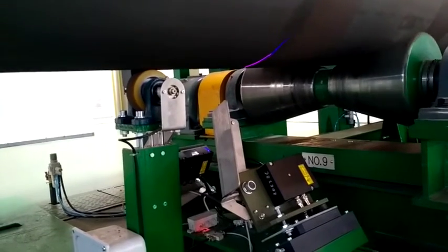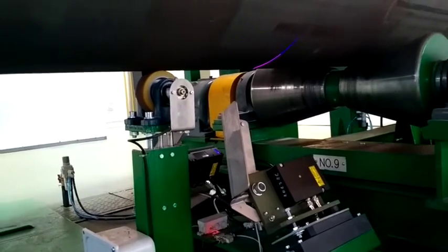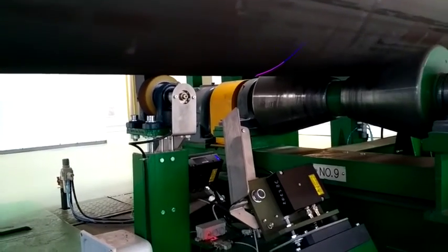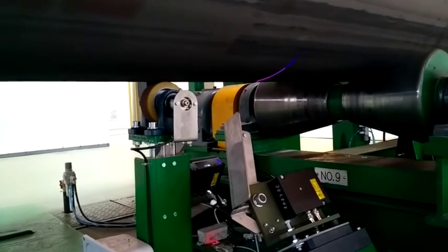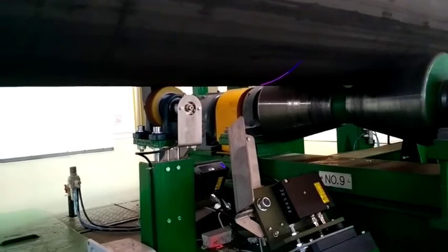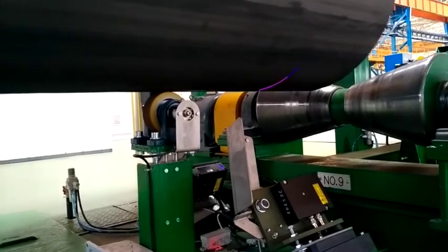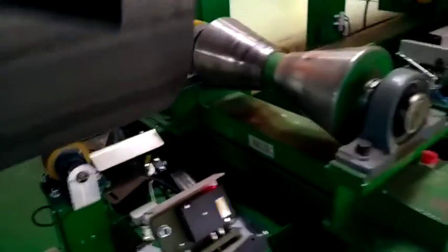In this case, you can see the work of the system to measure the weld. With the system, we can measure weld height, weld width, pipe profile deviation from the roundness at the length of 200 mm, displacement of welded edges. These parameters are measured by 2 sensors, whose laser beams are seen on the screen. One sensor works with the red laser, the second with a blue one. Before, of course, the sensors were calibrated and set in one coordinate system.